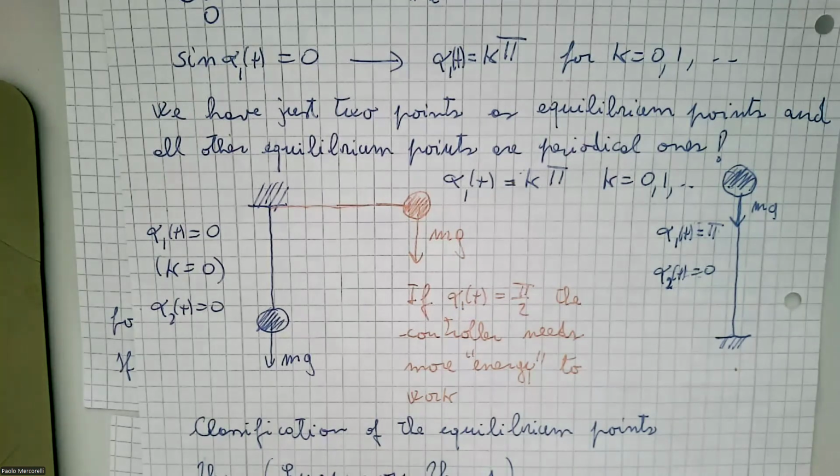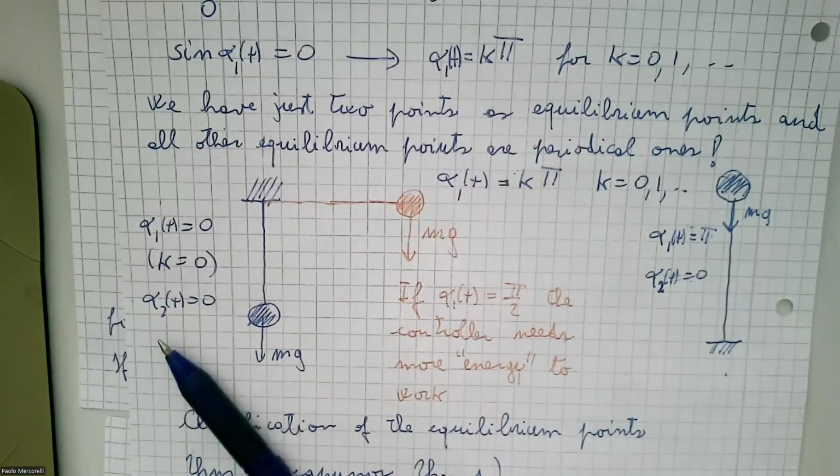But of course, I didn't consider now the trajectory, because the trajectory is more important in controlling the second theory. It's intuitive, no? Let me mimic. We are not in the presence in the lab. This means this equilibrium point is asymptotically stable, because if I move a little bit from the equilibrium point, I will come back to the equilibrium point with oscillation or without oscillation.